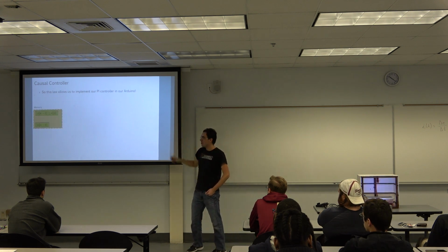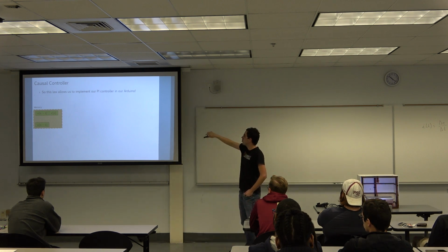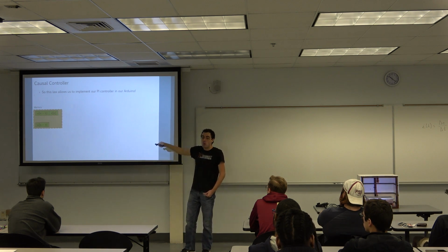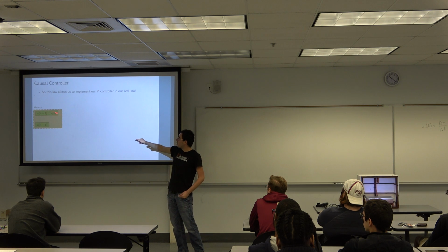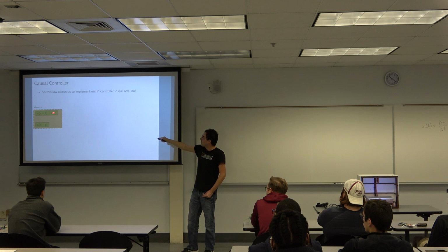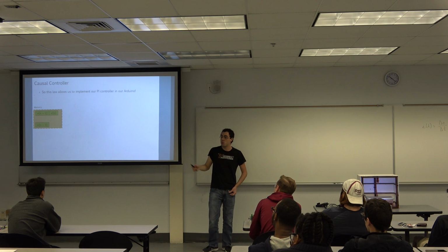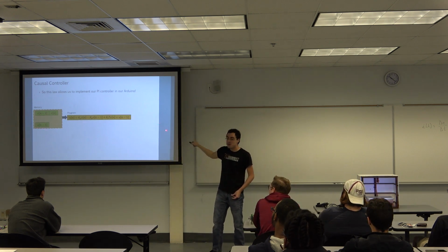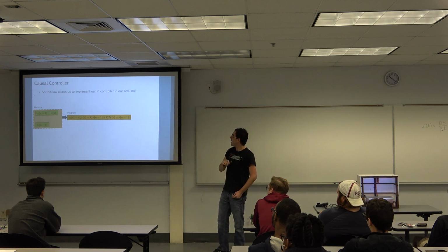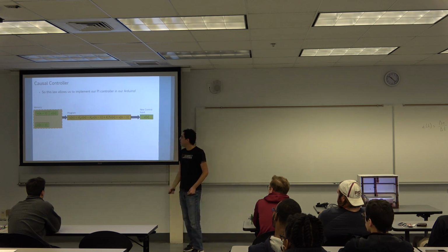So let's have a look at how a code controller would look like. We can have as much stuff as we want in the memory. So I'm storing in memory the relevant variables, which are e(n-1), the last error, the current error, and u(n-1). Those are the numbers that show in the expression. I use my fancy expression to compute that. This is literally one line of code, right? And I get the control input. I update my control input, and I loop around.